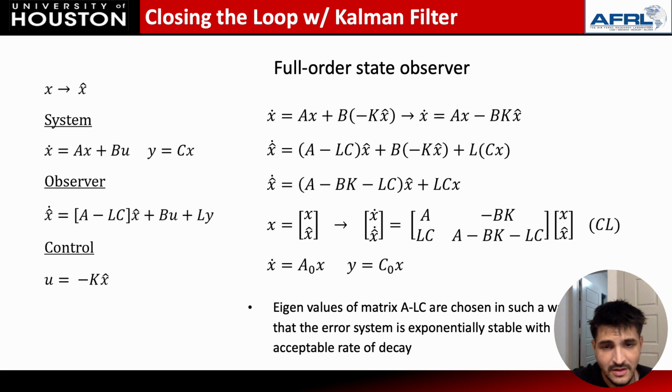And this also, it's just some more background information on the equations of how it works. So the A minus BK is again closing the loop with the gains from the LQR, minus LC, where the L is going to be from the observer gains from the LQE. And it forms the new state matrix, A minus BK minus LC, that determines the new stability for the eigenvalues.